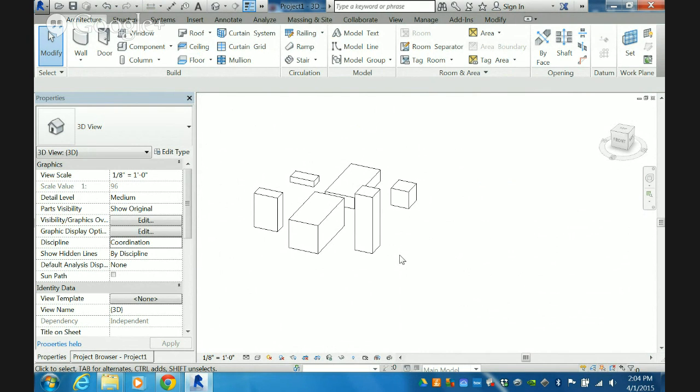But you could make the argument that design-wise, maybe you're putting different fabrics and different kinds of materials or textures on it. In that case, because you've got such a high variety of textures to go with those awnings, that would be a perfect example of developing an instance parameter. In this case, it would be based around materials, which, speaking of which, is a good idea. Let's talk about one other parameter type, and that's the material parameter. And we'll apply it to this block.